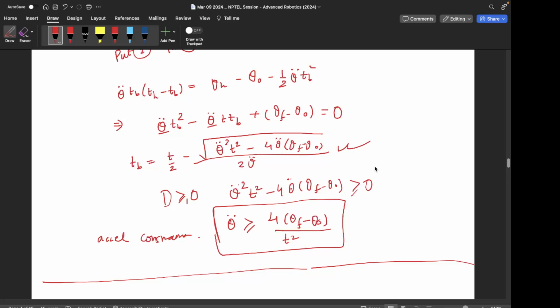We saw how to use cubic polynomials, and also polynomials like the linear function with parabolic blend. This is what we call a spline. It's up to the choice of the person and the requirement of the task which kind of trajectory is suited for that specific problem.